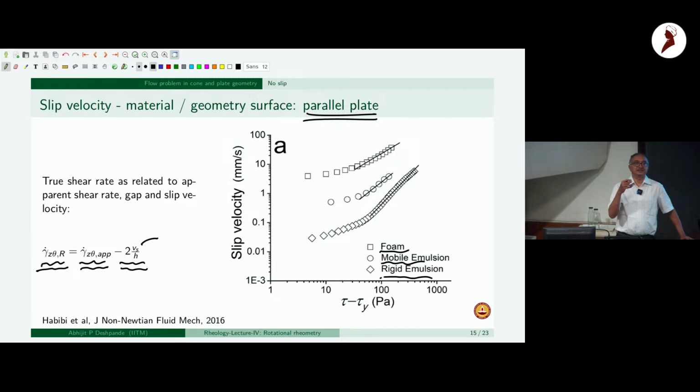And so the shear rate correction is basically this slip velocity divided by the gap. Given this hypothesis, you can plot your data against 1 over h. So as he mentioned, you do the analysis with respect to how you are changing the gap and what shear rate you observe, and then plot this and back calculate the true shear rate as well as the slip velocity.